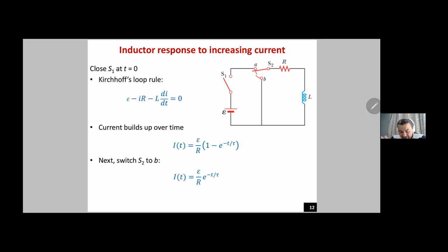In the capacitor, we were treating the voltage as the continuous value. However, in the inductor, we will be treating the current as continuous, while the voltage can change abruptly. In the capacitor, the voltage is continuous and the current can change abruptly.